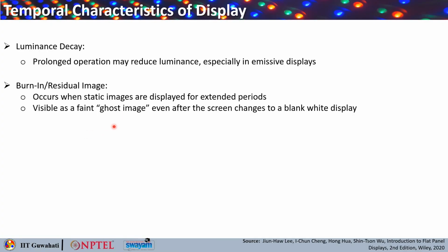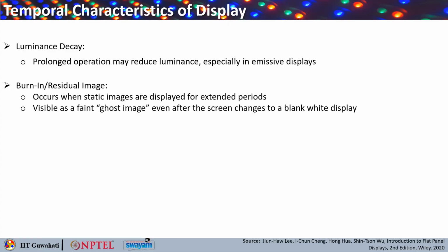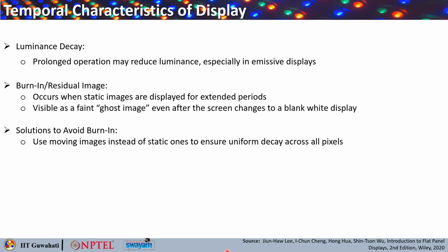This is one major drawback in OLEDs, and this happens when static images are displayed for an extended period. A visible faint ghost-like image will start appearing on your screen whenever you change your screen to a blank white display. So the static image gets imprinted on the display. This is called burn-in or residual image.